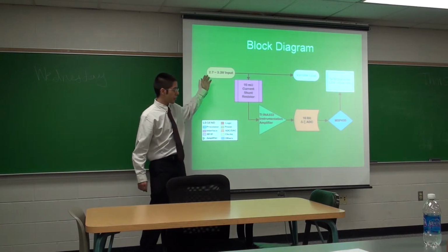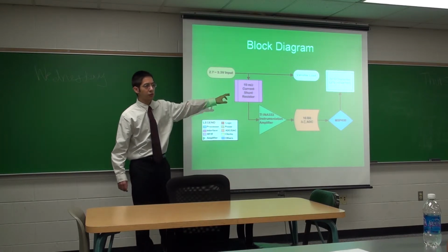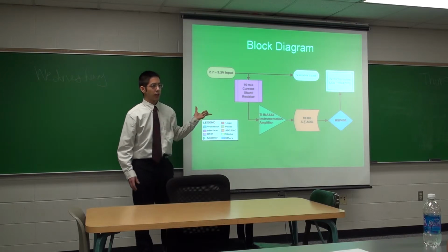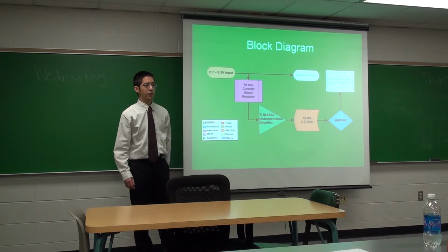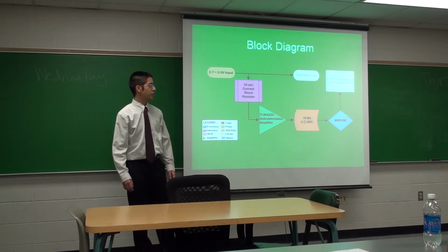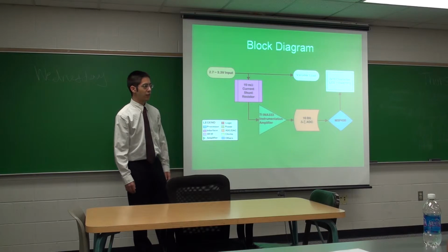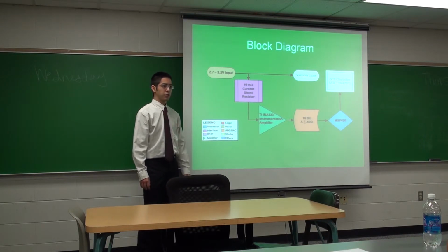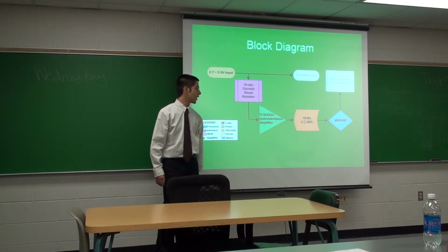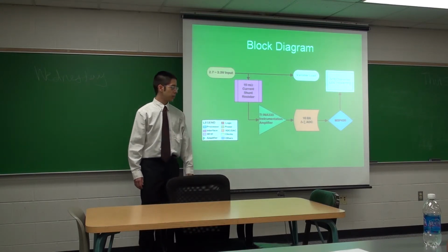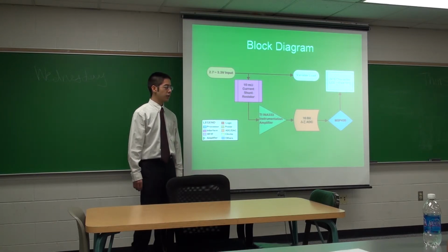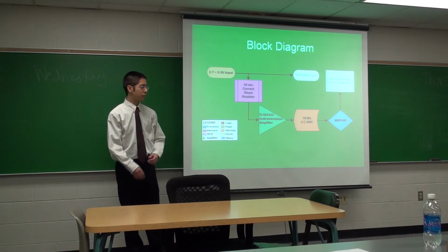Again, our power source is up here. The variable load would be our cell phone. And we put a current shunt resistor in series with the two so we can have a voltage drop across it when there's current flowing. We have current in the 100 milliamp range, and this is a 10 milliohm or 25 milliohm current shunt resistor, which gives us microvolts. So we need to amplify that using a Texas Instruments INA333, which is a very precise instrumentation amplifier, which has about 10 microvolts of offset, so this should allow us to get accurate readings.